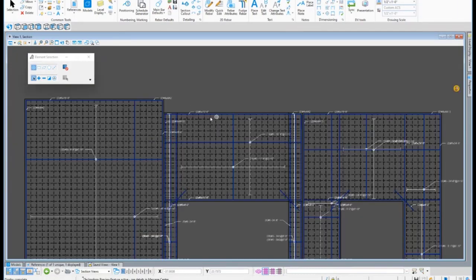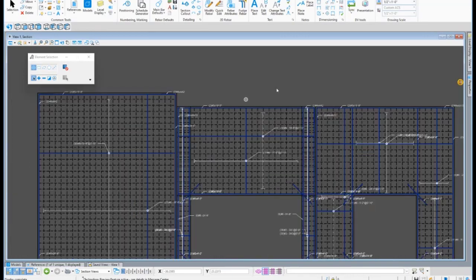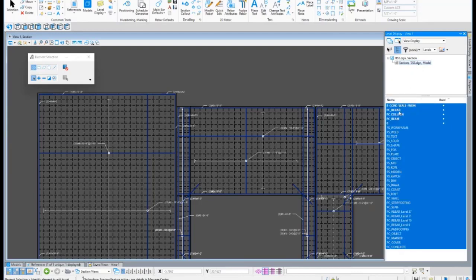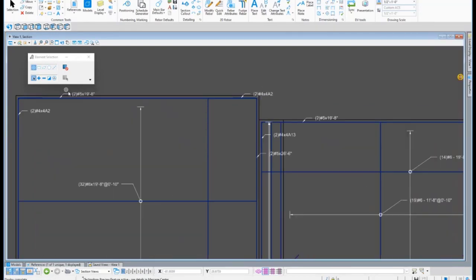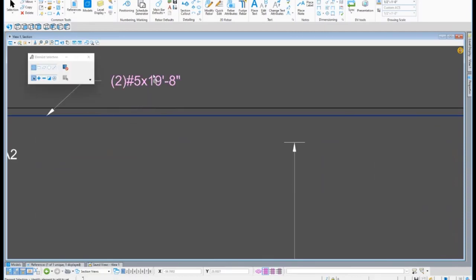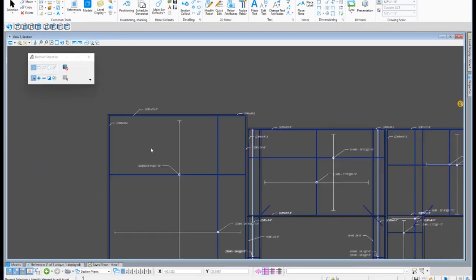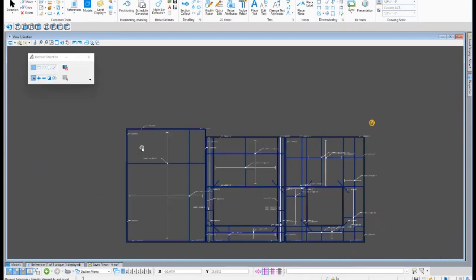You're able to still utilize the Bentley auto label tools, so then you're just simply cleaning up a drawing. If I would have saved it with a rebar off, I wouldn't have had to have done that step. And then it's just a matter of moving the items where you want it, positioning what you want where you want it, just dragging and dropping, making any changes, cleaning up the drawing, dimensioning, and then placing this straight onto your sheet. So you can see how using a parametric cell could speed up the process of taking that basic design, tweaking it just a little bit, creating the sheet, creating the section, putting it over onto the sheet and moving on.